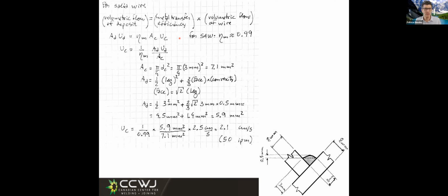And this, which is in your notes, you can follow. You can follow this calculation, do the numbers yourself, and it's going to give you the wire feed speed for this problem. This is extremely powerful. These types of parameters are typically decided by tinkering.